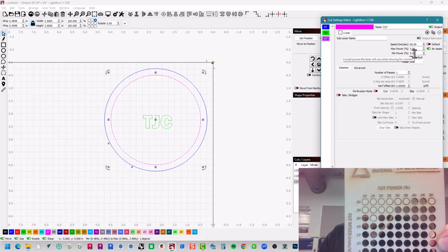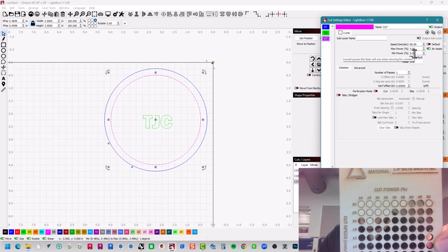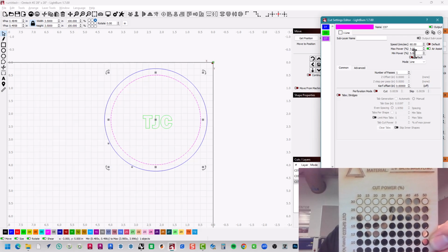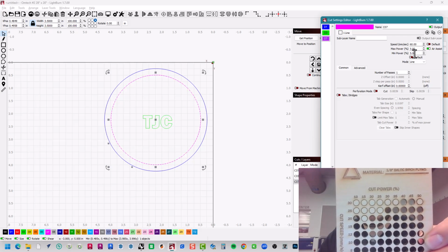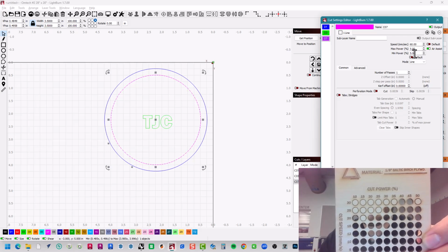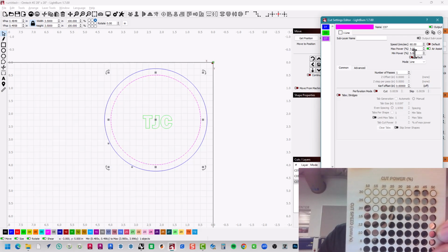All four wheels are not necessarily moving at the same exact speed when going around a corner or making a turn. The inside wheels are usually going slower, while your outside wheels are having to do more work because they have a further distance to travel. So I'm going to do 60 and 5 and 5. The idea is I'm going to go twice as fast as this very first setting, so I hopefully don't cut through, and also use half the power that this setting has.